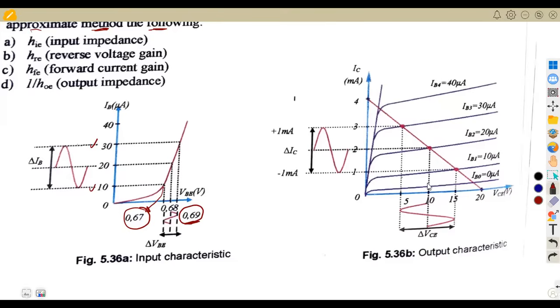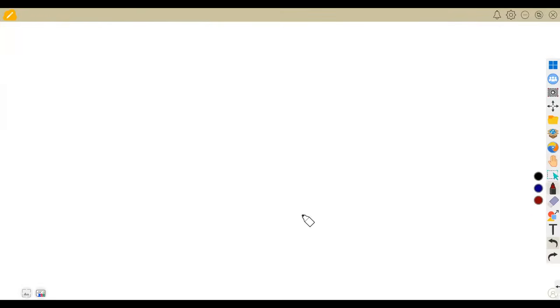Then for the output, we talk about the voltage between the collector and emitter, the output current being the collector current. That's for a common emitter. All right. Remember this diagram, guys. We talked about this from our N3. The diagram of a common emitter amplifier is like this. I'm just going to have a sketch. So at the input, we're just going to have a capacitor here. Then we've got our voltage divider from the two resistors. This one is too big. I'm just going to have this as a sketch, guys, for our common emitter amplifier, so that we understand each other.